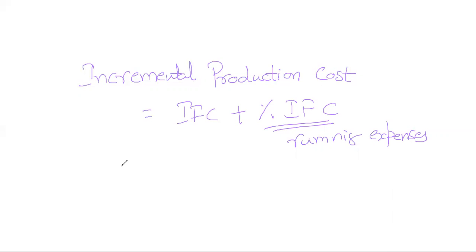Generally the cost expression is taken as a simple expression for our ease of analysis. So the standard representation of this cost function is like this: Ci equals ai plus bi Pgi plus ci into Pgi square, where Ci is the cost, fuel cost, or it is called the input fuel cost. ai, bi, ci are the coefficients. Pgi is the power output expressed in megawatt.